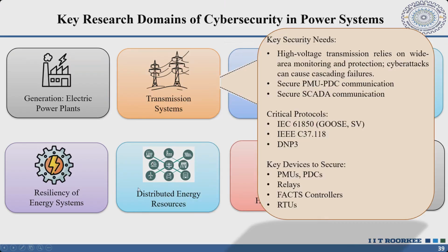The next is the transmission sector. When power is generated, the data is transferred by PMUs and IEDs from one end to another end. So there is peer-to-peer communication between PMU and PDC, and secure SCADA communication. The protocols they are using are IEC 61850, basically the GOOSE and sampled value based protocols, IEEE C37.118, which is a protocol for communication between PMU and PDC, and DNP3, which is used by the SCADA system. And the key devices are PMU, PDC, relays, PACs, controllers, and RTUs.